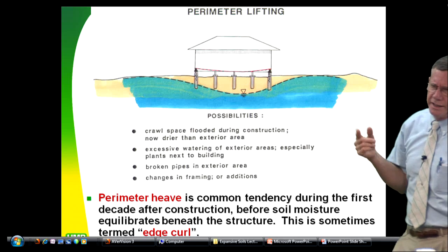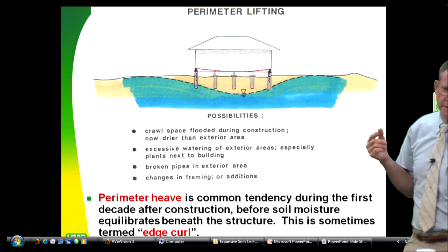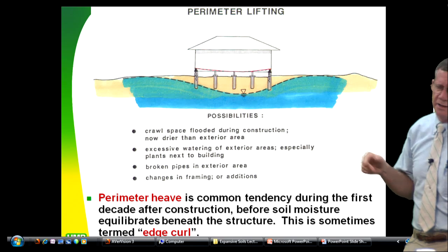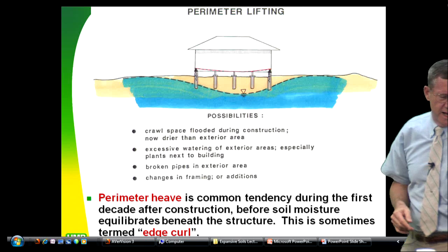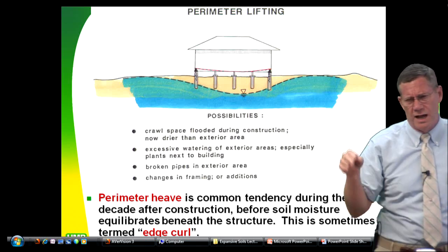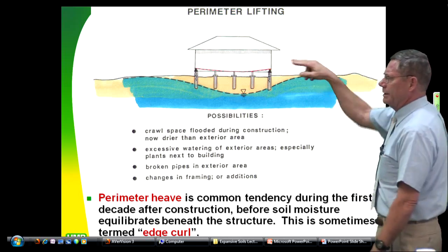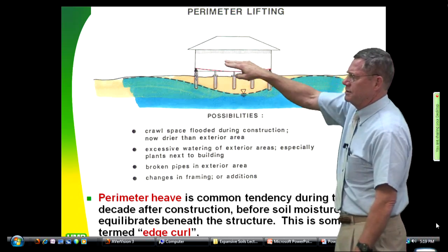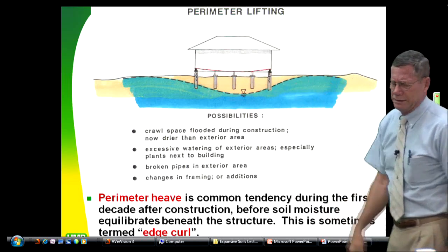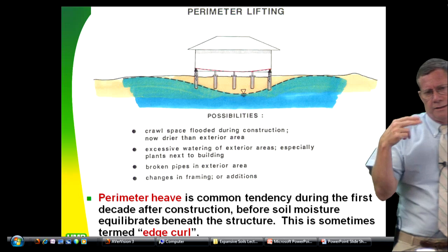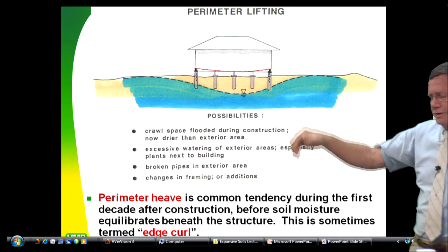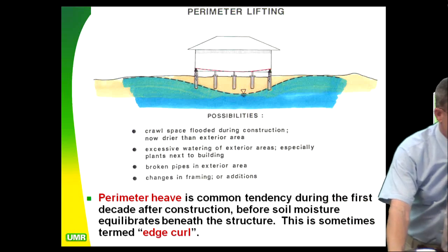And these are actually accounted for in the International Building Code in Chapter 18 and in the PTI manual, the Post-Tensioning Institute manual for post-tension slabs on grade on expansive soils. So you actually have to design for that; the controlling parameters are edge curl and interior doming, because you're going to get a moment change when you go to interior doming later. So this thing's going to actually end up having a W kind of shape, and as long as delta L over 180 isn't exceeded, you have tolerable tolerances for that bending.